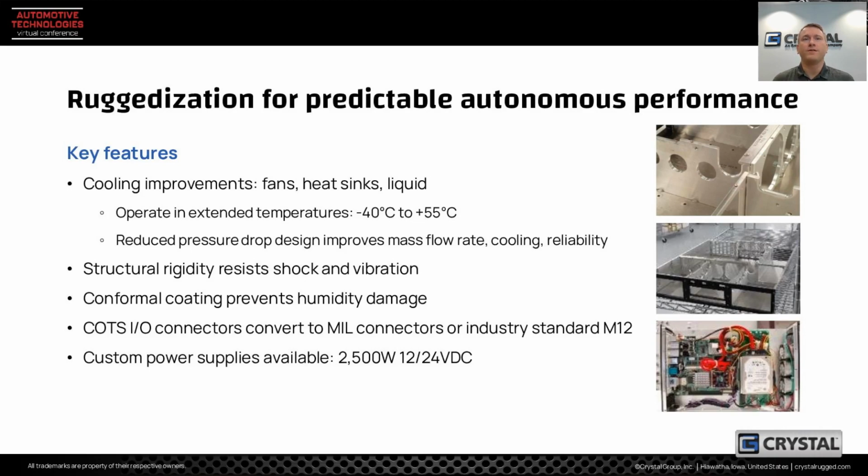Another part of the headache that the industry is fighting with is that alternator power is not good, clean power, and data centers have nice, clean AC power that does not require high durability power supplies to run the equipment.